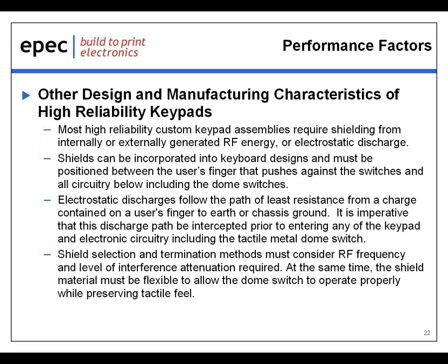Suncoast Digital Technology can incorporate effective shielding into keypad designs. The shield material must be positioned between the user's finger that presses against the switches and all the circuitry below, including the dome switches. For electrostatic discharges, the discharge path follows the path of least resistance from the charge contained on a user's finger to chassis ground.